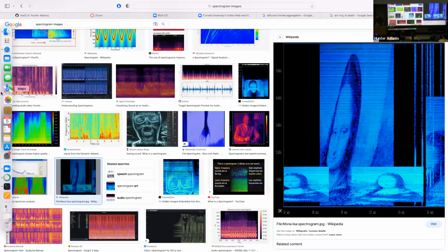You could do speech vocoders. So this is kind of interesting. So suppose you talk into the microphone, and you want to figure out the frequency content of your voice. One method by which you could do that is compute an FFT, and that tells you all the frequency content of your voice. Alternatively, what you could do is set up a bank of filters that sort of overlap, so that there's a bandpass filter for this range of frequencies, an adjacent bandpass filter for this range of frequencies, and so on and so on. And each of those filters would output the approximate amount of power at that range of frequencies.